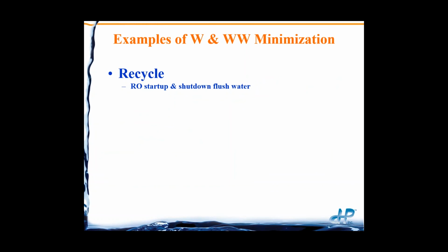Other things as far as water and wastewater minimization, if there is a cost-effective way to recycle certain water, so recycle using it for something else, you can. Like ROs at startup, typically for higher purity systems, your permeate dumps to drain for a minute, 2 minutes, 3 minutes.